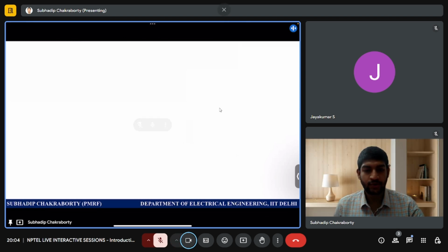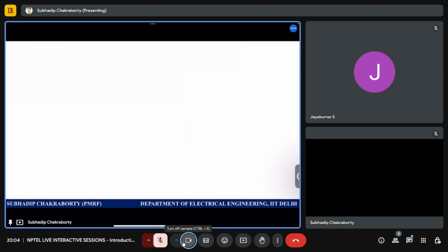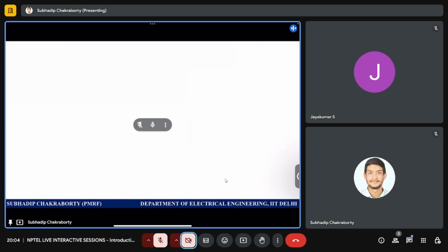Up to that we derived the expression in terms of delta and theta S. Now let us derive dP by d delta, with respect to delta. And theta S we assume not varying, right? So we'll find EF VT by ZS sine of theta minus delta minus 0, because cos theta we assume constant, right?